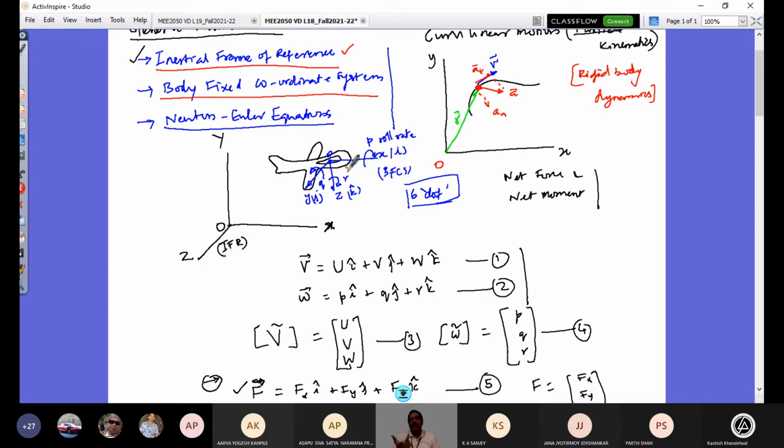The coordinate system is the rectangular coordinate axis system, or you can say Cartesian coordinate system, fixed in the body, where you have your right hand, three fingers stretched in this fashion. The index shows the forward direction X, the middle finger shows the lateral direction, and the thumb shows the downward direction. These are positive directions. This is essentially the axis system we are going to look at in our ground vehicle as well for lateral dynamics study.